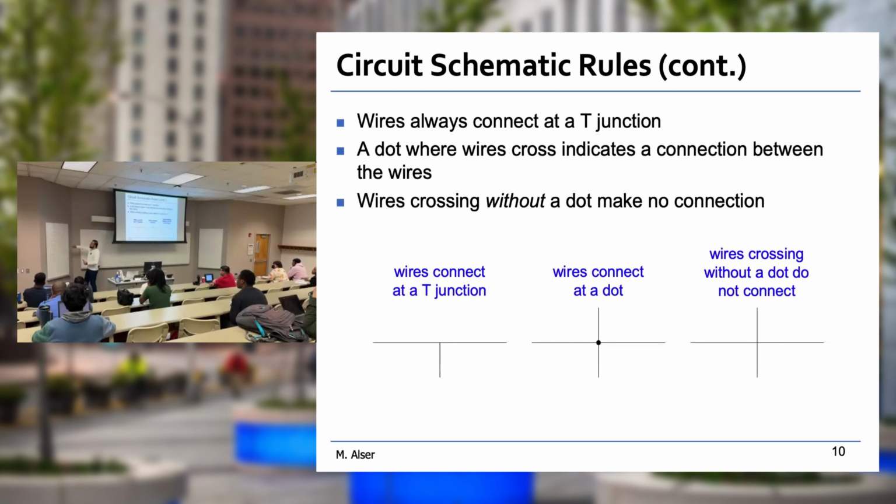So remember, we want to use 90-degree wire connections all the time, right? So don't ever make it this way, just random drawing. Don't do that. And whenever we want to cross another wire, it's up to you. You could cross it straight, or you could make an arc or curve over there, and that indicates that there is no connection. Okay, so it's up to you. In three ways, all of them are correct. You could cross it directly. It still means there is no connection.